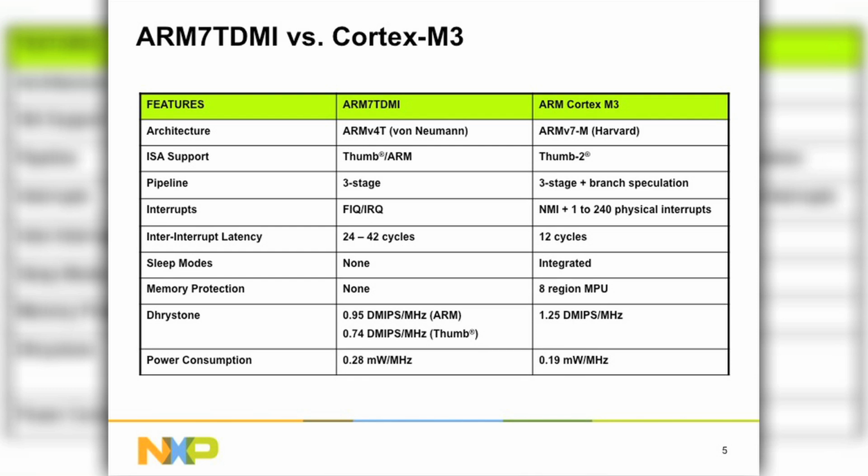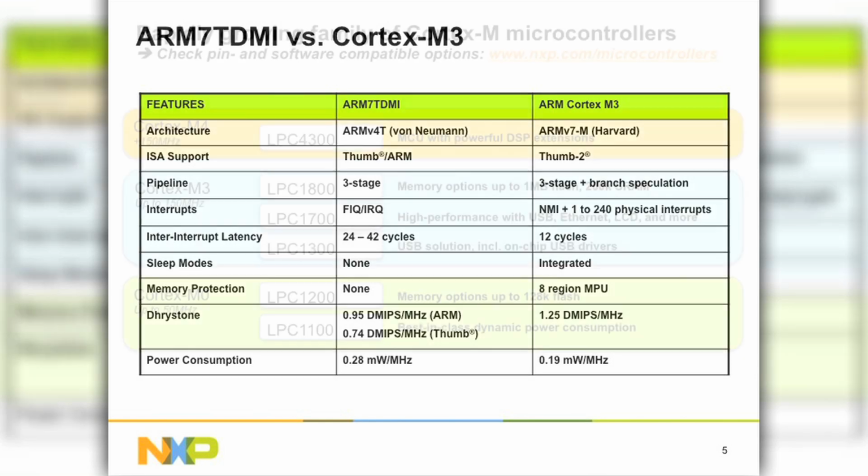One catch, however, is along the way, they changed the instruction set. So if you're starting with an ARM7 design, moving to a Cortex-M, if everything is in C, it should be more or less a case of recompiling. But there are slight differences in the instruction set, going from the thumb instruction to the thumb 2 instruction set. The good news is once you've gotten to the Cortex-M family, all of the M's are based on that same instruction set. So the M0, the M3, and the M4 all are code compatible.